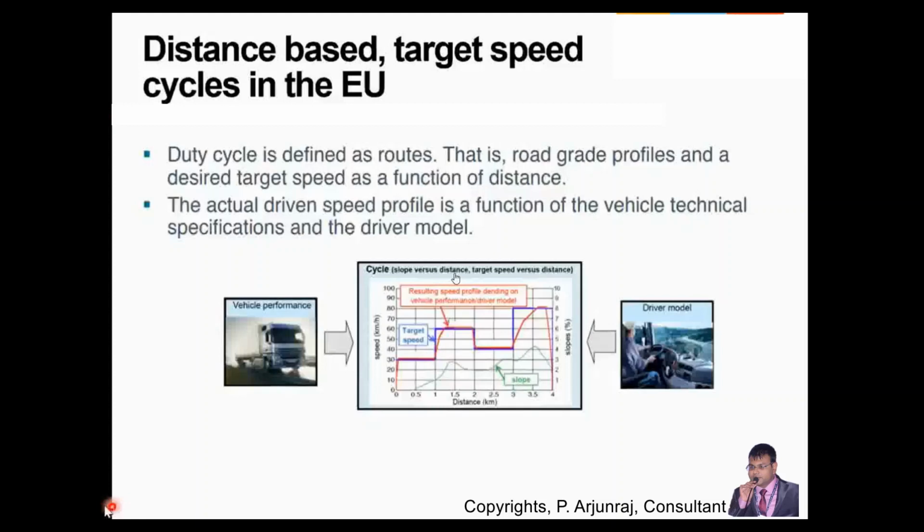You can also measure the tire wear pattern after completing so many kilometers. You can measure the tire wear using your depth gauge meter and compare. You can also extrapolate the wear, from the initial wear at 0 kilometer to the wear at various intervals, maybe 2000, 4000, 6000, till the tire life. Say, for example, the tire life can be 40,000, which is going to be the warranty.